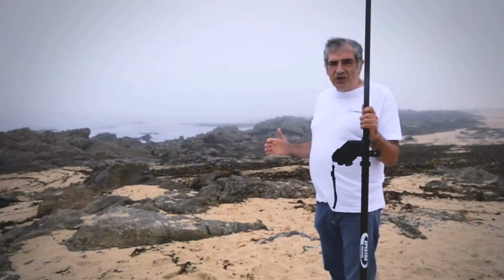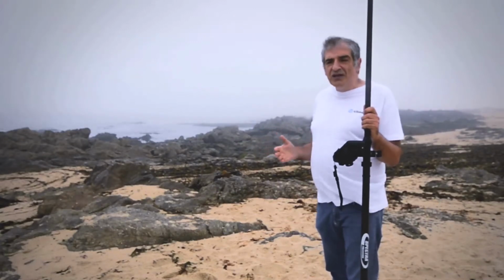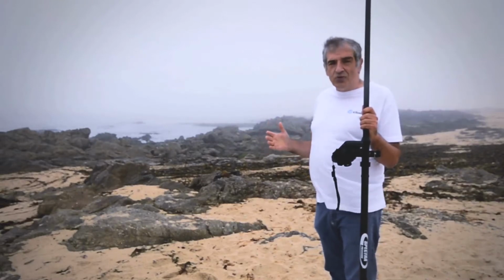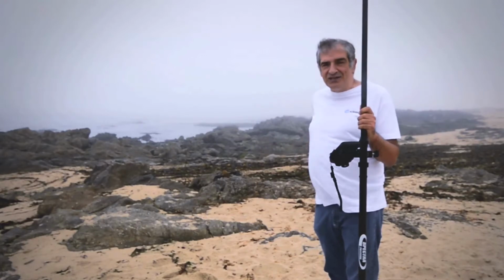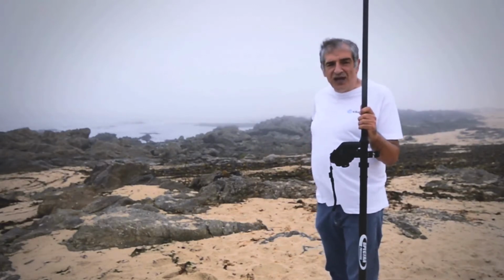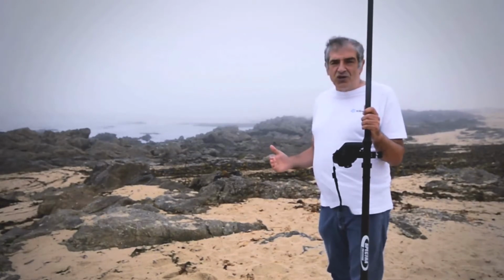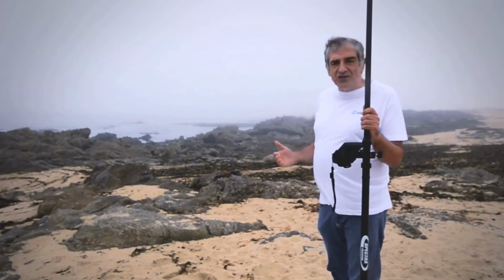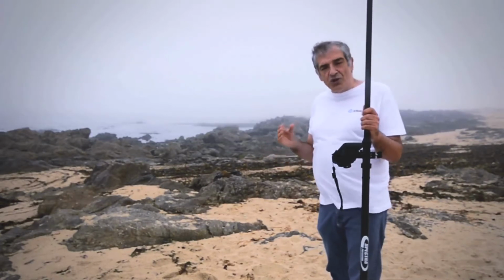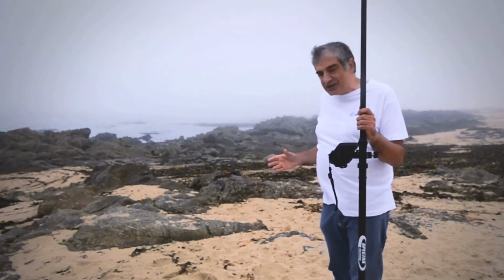The drone will acquire a set of images, probably a few hundred, that cover our study area. We need to mosaic them, to join them all in a single image, and that needs to be georeferenced with a very good accuracy, because our images will have a resolution of 1 or 2 centimeters, and we need to know its georeferencing with a very good accuracy so that we can overlay images from different times.